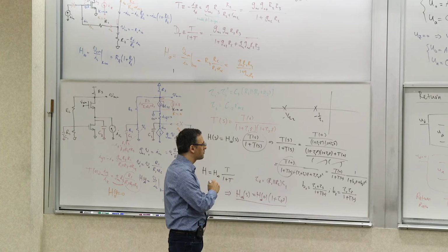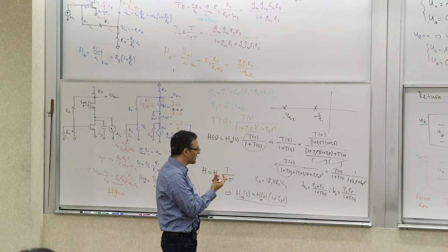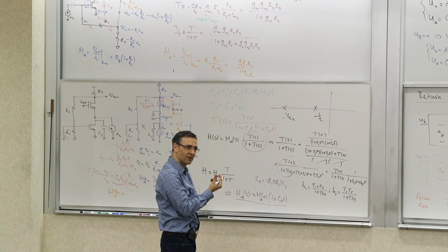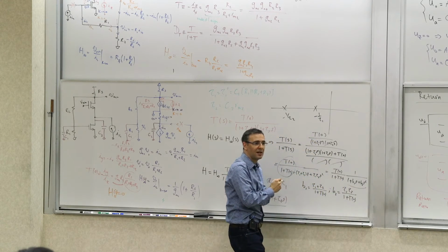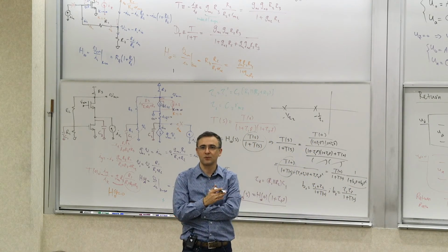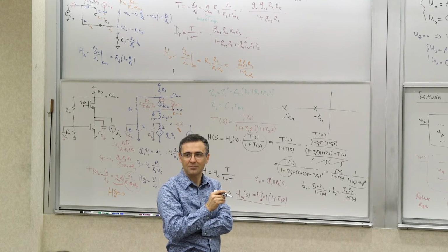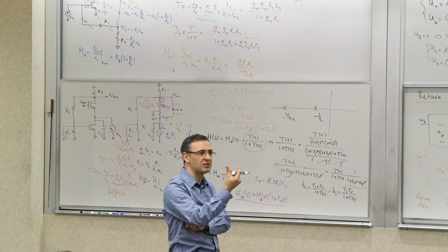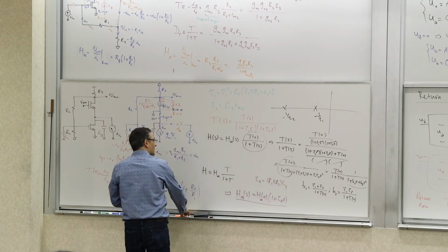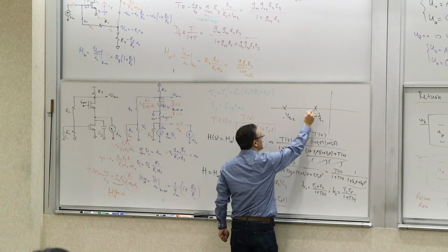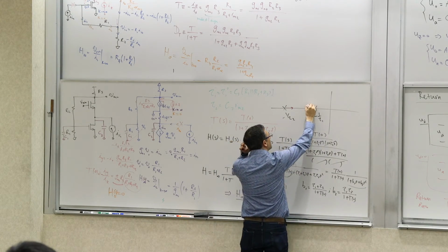You can see where they are with respect to each other. You can think about it different ways. You can look at the Q of this thing and see that the Q is actually increasing. Or you can think about it as a quadratic equation and calculate b squared minus 4ac, what's under the square root, and see what's happening. You'll see what's under the square root is actually decreasing as you're increasing T0. So as you're increasing T0, the two poles start moving towards each other.